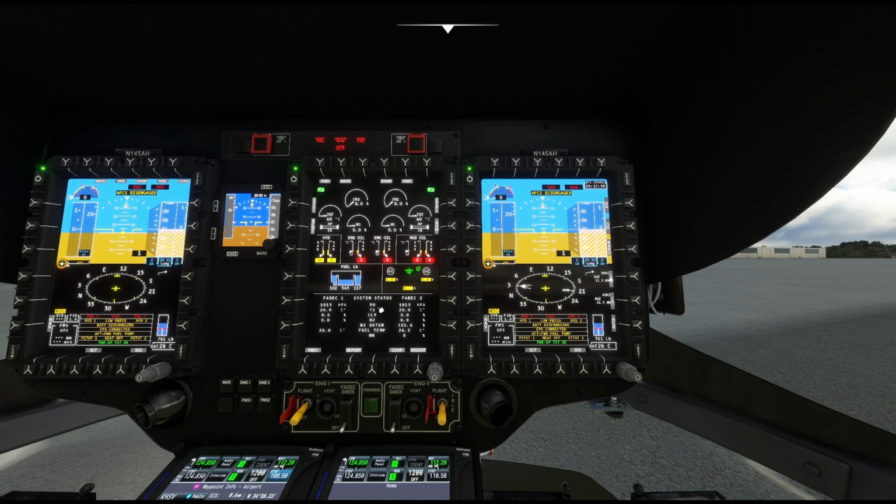So the FADEC has its own ambient air pressure sensor, so this value should match this value. Your T1 value should be reading the same pressure as the system that is producing this. Now we have to put this in so that it knows how to convert that pressure into a number, but the actual raw pressure being received by the system is the same.